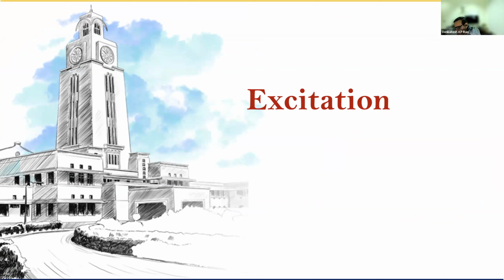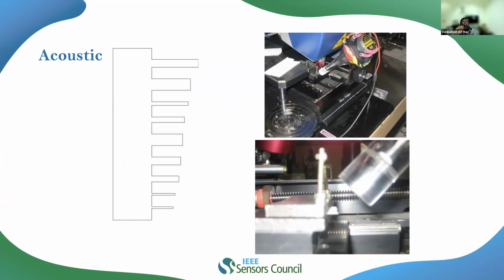So the different excitation techniques that we can have: one is that you can go by electrostatic excitation, right? Whenever you go by the polymers process, you get a top electrode and a bottom electrode. Then you can easily actuate it by electrostatic means, correct? On the other hand, if you do it by the SOI process, and you are having comb drive resonators, absolutely no problem.